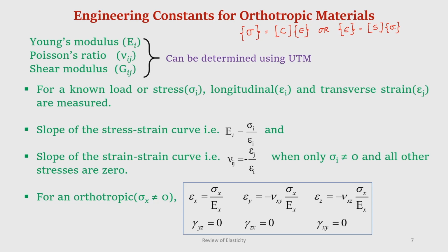To characterize a material subjected to stress, if we want to know the strains, we must know each element of the stiffness or compliance matrix. However, these elastic constants are generally not measured. The quantities actually measured in the laboratory are termed engineering constants, and there are relationships between the engineering constants and these elastic constants. The elastic constants are expressed in terms of engineering constants.